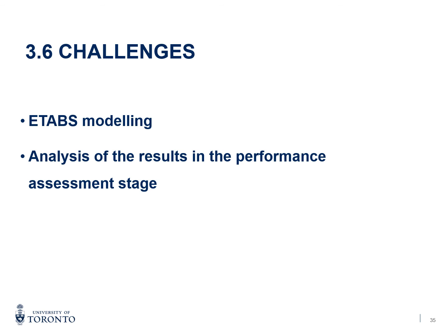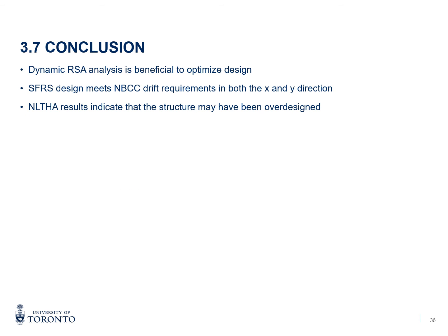After completing all the design stages for this project, the following conclusions can be made. The dynamic RSA analysis is important and can optimize our SFRS design and have an impact on the overall cost. The SFRS design under the nonlinear time history analysis meets the NBCC drift requirements in all directions. The nonlinear time history analysis results indicate that the structure may have been over-designed.